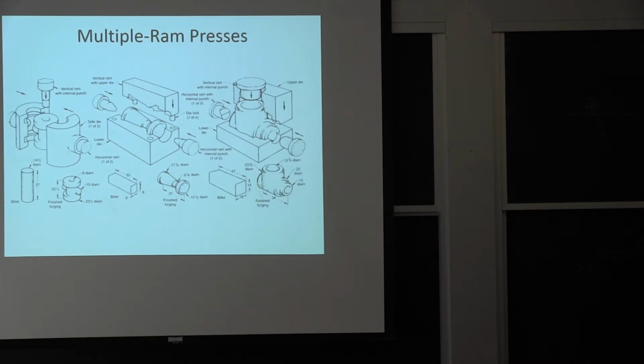It's not only more complex to set up in terms of getting a consistent quality. The consistent quality here, whether it's hot or cold, how the material is going to behave is very different depending on the alloying and the prior history also. So it makes it very challenging, and it's only used for high volume application where you can afford the extra cost to get better properties than you get out of castings, for example.